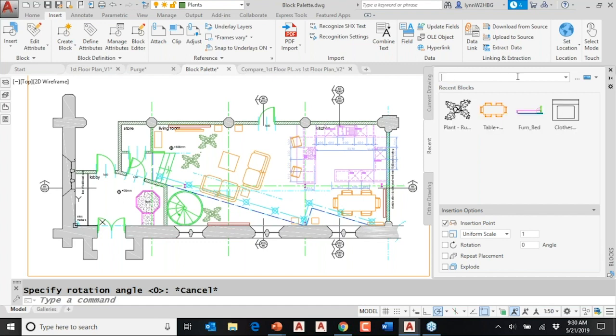And if you don't remember your old wildcards, if I did it like this, let's see, it has the word bed in it. So there was one block that has the word bed in it. That's everything. So it can start with anything, but it has the word bed in it. So you're gonna have to brush up on your wildcards.